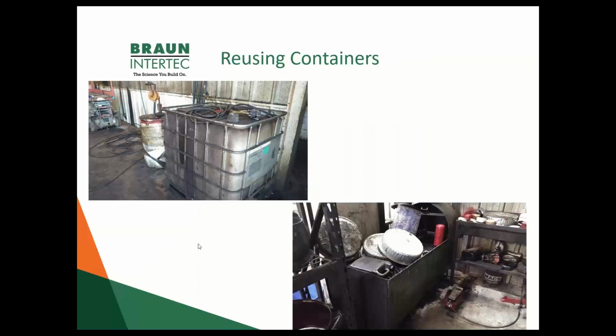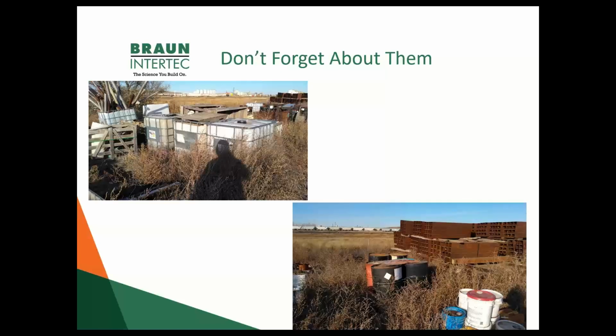Reusing containers. It's great to reuse containers. Make sure that when you use them, they are suited for that new use, and that you have relabeled them as well, so that it is clear that these have been repurposed and that they have a different material than what they originally had in them. Don't just load them up and then set them out back, because full containers still have to be listed in your total containment capacity volume, and if they're set out back and forgotten about, that is just waiting for them to eventually rust through and create a problem for you in the future.